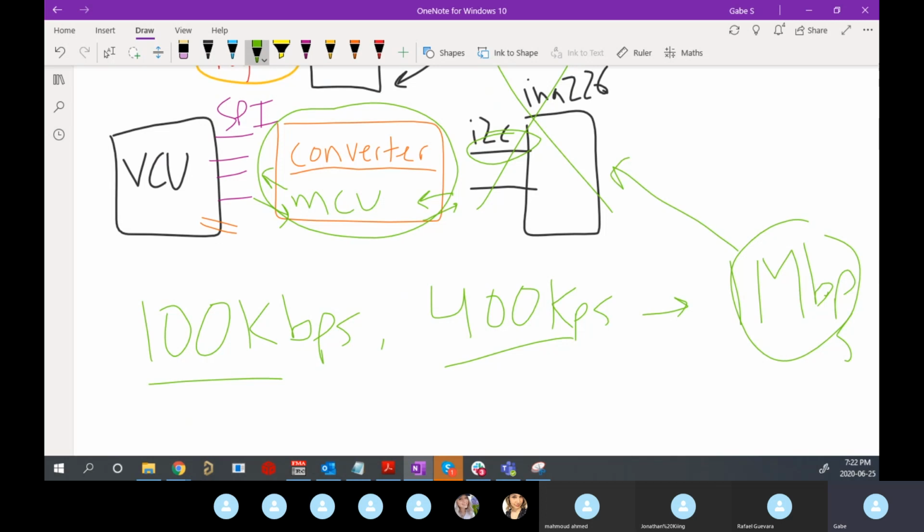Whatever you're using is going to basically define the window of speed you can go. And so this will just tell you at what speed your clock line has to be, right? SDA will then have to toggle at 100 kilohertz or 400 kilohertz or 1 megahertz to send things back and forth.